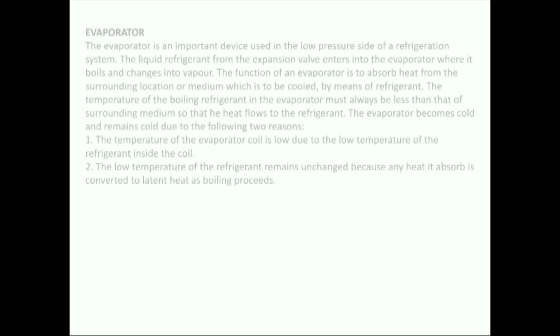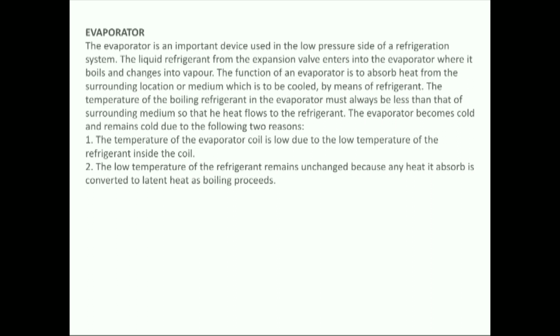Evaporator. The evaporator is an important device used in the low-pressure side of a refrigeration system. The liquid refrigerant from the expansion valve enters into the evaporator where it boils and changes into vapor.